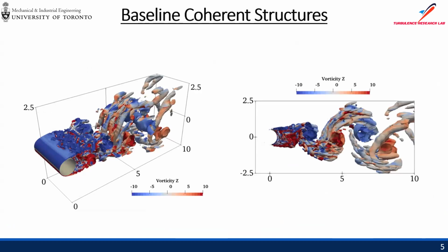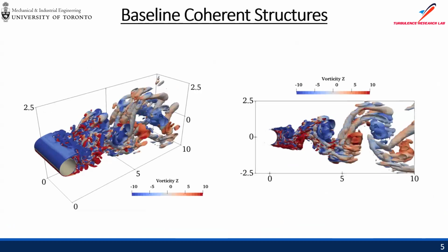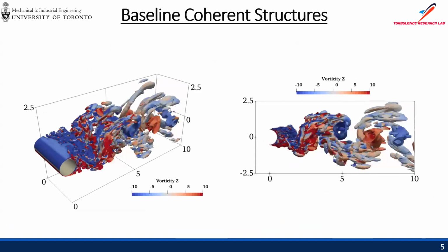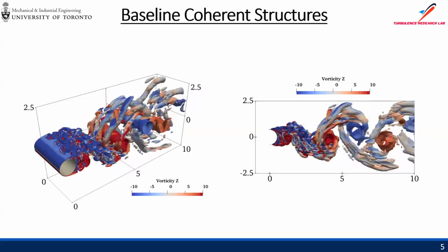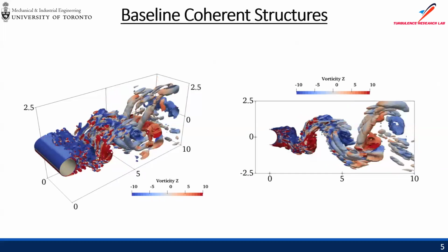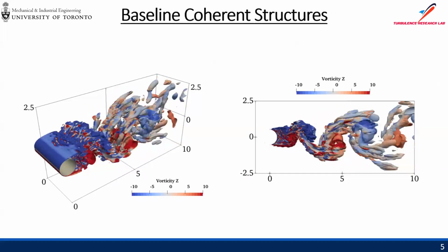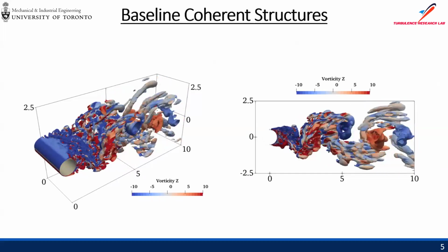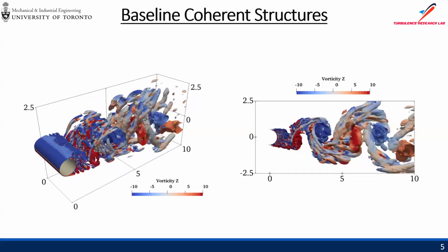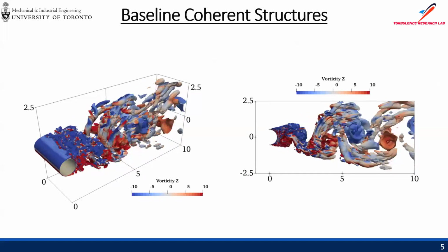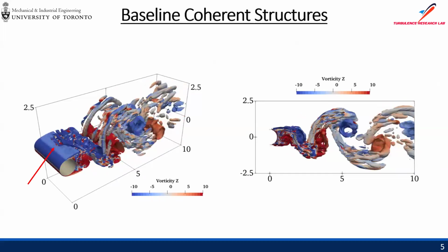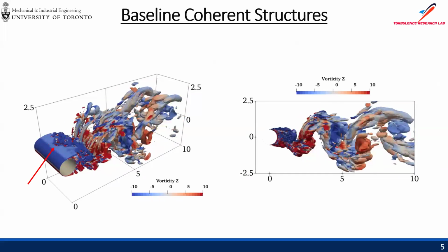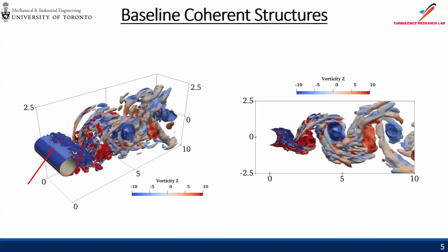So I'm going to start the results section with a Q criterion contours animation. Quite often this is used to look at the flow structures around certain geometry. On the left, we have the isometric view. On the right, we have the side view, which is basically the same as the top-down view. Starting with the left, we have a laminar separation, but then the flow transitions to turbulent.